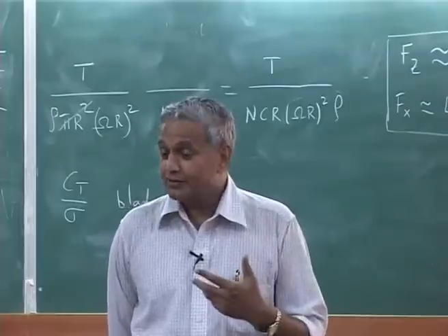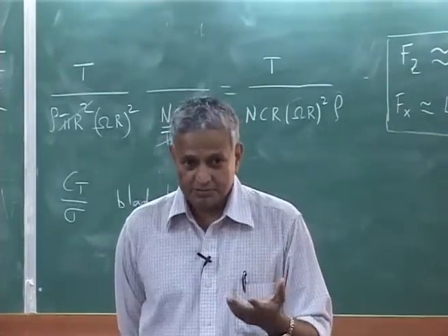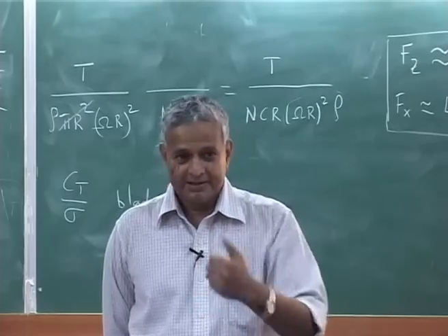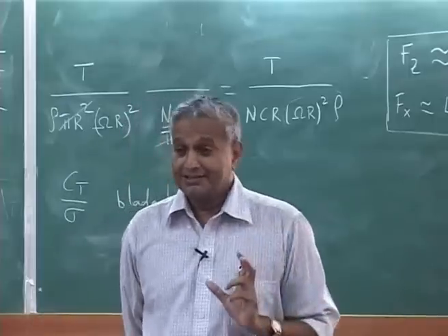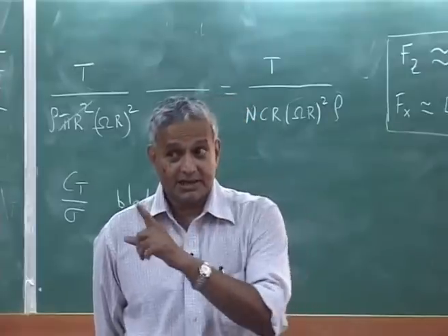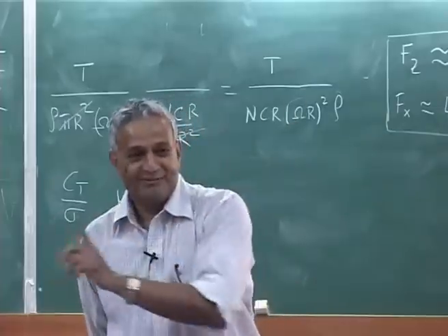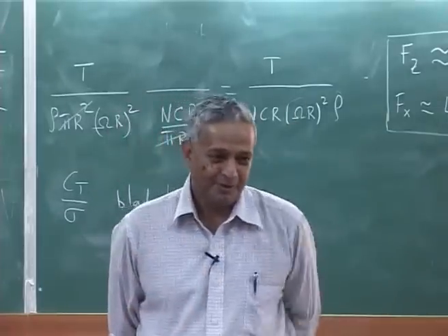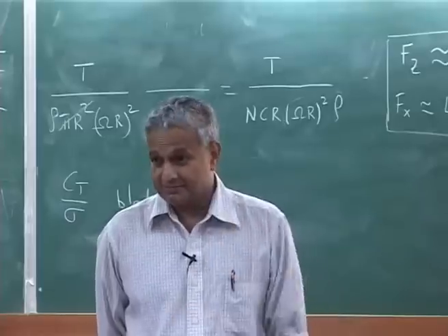Now, this is true even for forward flight, but in forward flight you also have to lift the weight, in addition to overcoming drag, etc. Now, industry requires this CT over sigma. It is not a constant with forward speed, please understand, this varies with forward speed. This is what I gave you as a project, because this is very tricky stuff.